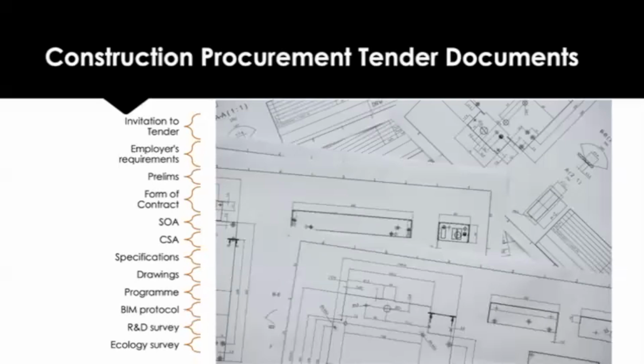Other things you might include in there are things like planning and managing construction work, any communication and liaisons, security, site holdings, transport to and from site for their workers, permits to work, fire precautions, emergency procedures, a means of escape, parking, smoking, confined spaces.